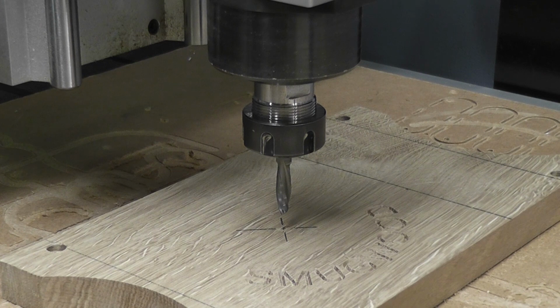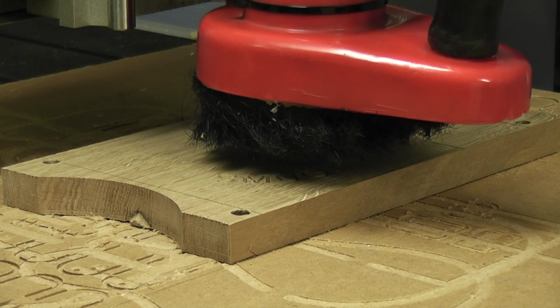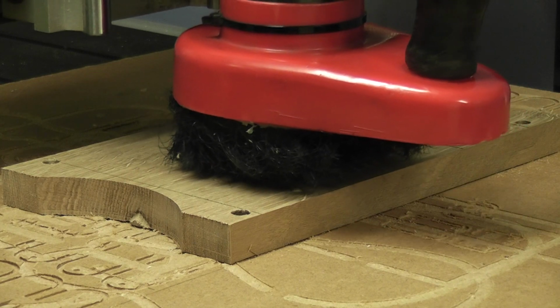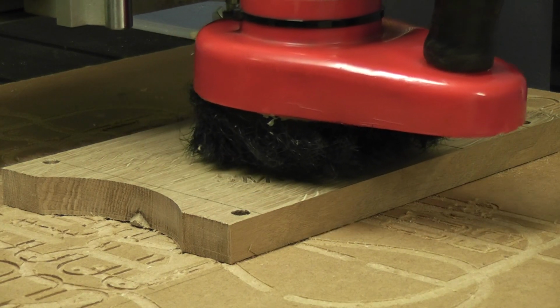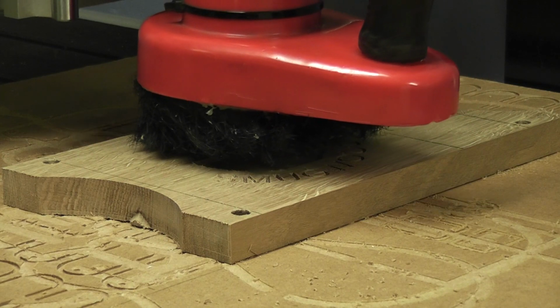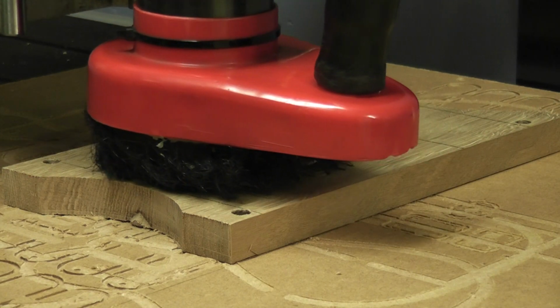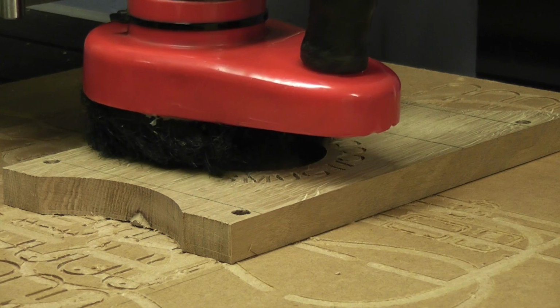Once engraved, the downcut spiral goes in and the rest of the machining can be finished with just the one cutter. I've also changed my toolpath to the buttonhole cutting so it removes just a few millimetres at a time and moves to the next hole. I can then use a vacuum or an airline to remove any chips that may cause problems with the cutter, but on this occasion everything went quite smooth.